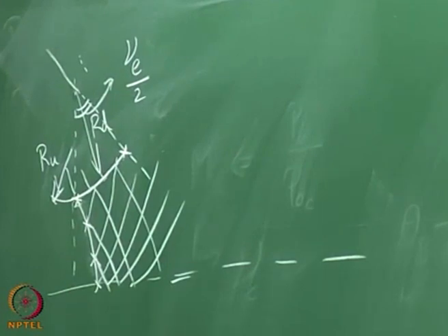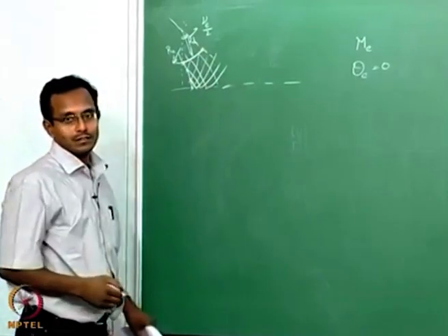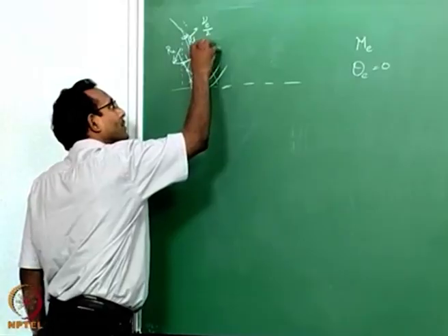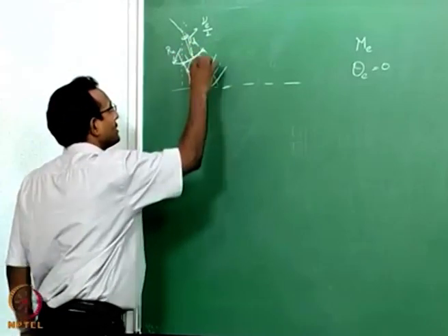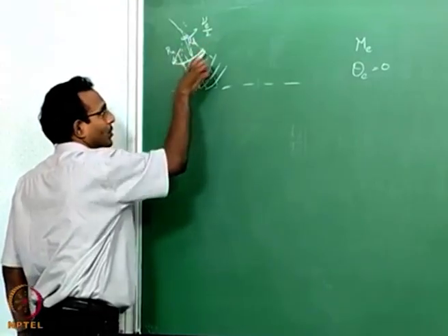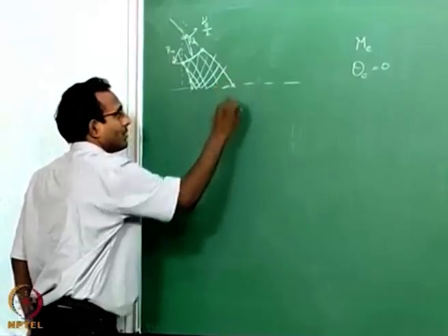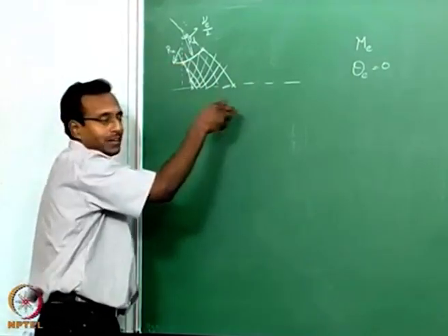But now I am going to say, after this point, I want to do something very different. So, if I consider a right running characteristic that is coming from the last point on this circular wall, when it hits the axis or the symmetry point, I know that it is a negative characteristic.